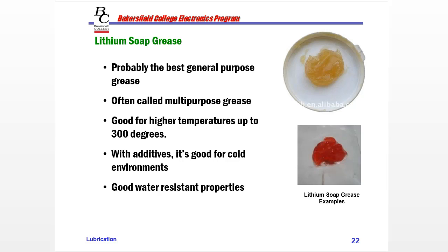And so we use lithium and an actual synthetic, which we'll be talking about in the next couple of slides, which has really good water resistant properties. So I wouldn't want to use a sodium type of grease, because what is snow? Well, snow is a little more solid form of water, but that snow's going to melt and that would wash the grease out. So need to use a grease for the intended purpose, whether the location is wet or dry. That's very important. And it's good for higher temperatures.